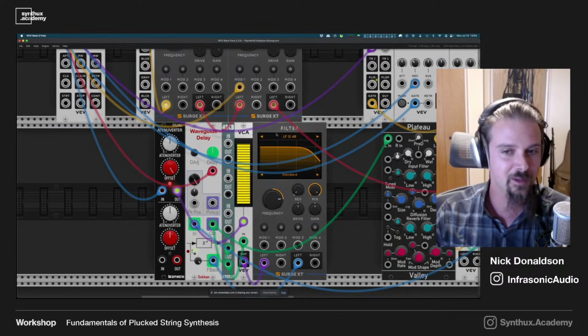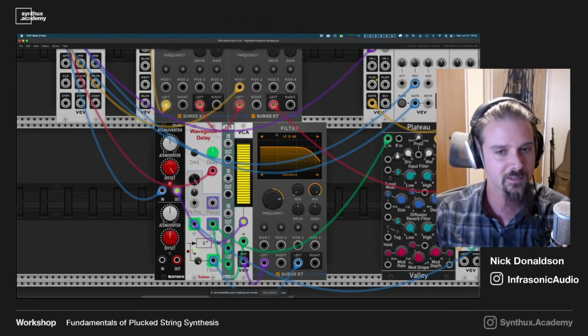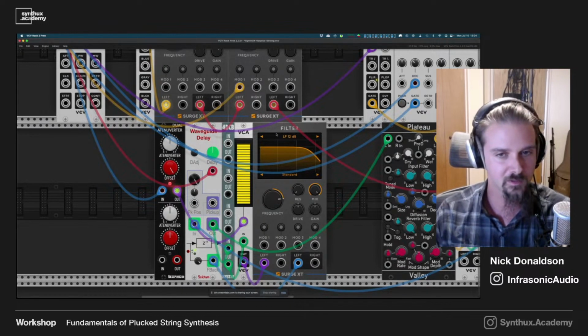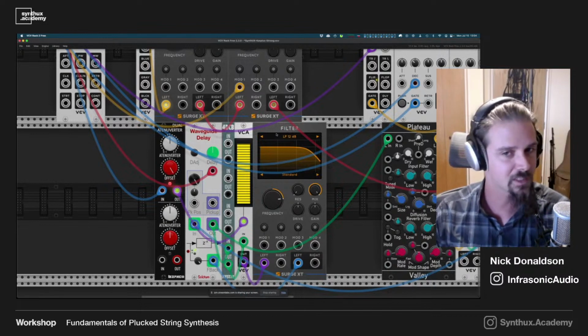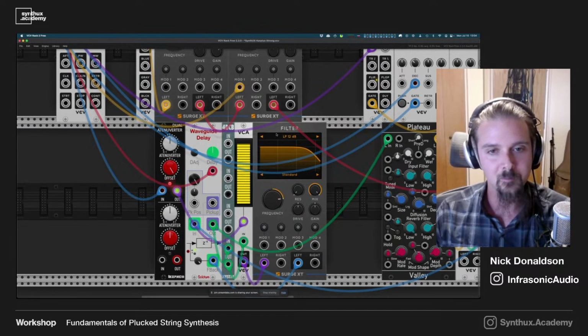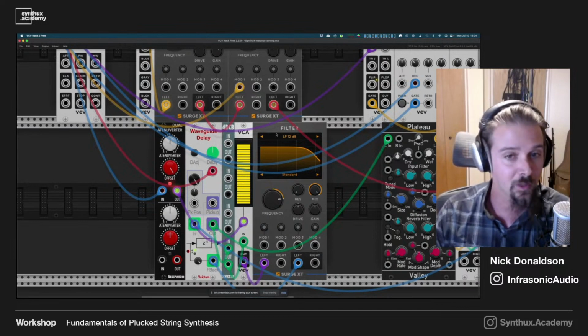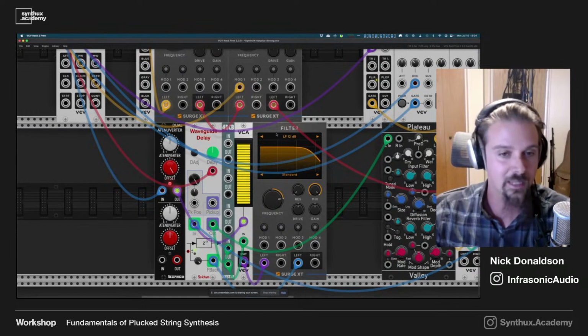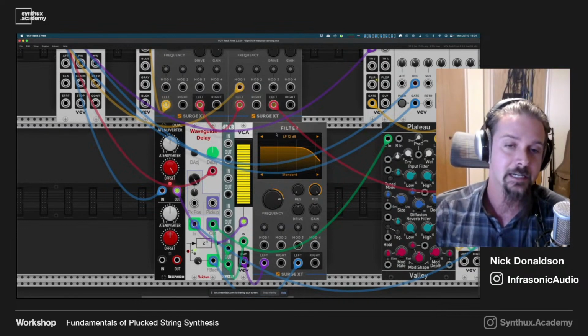I know that's maybe not the best explanation, but it's a little difficult to explain without really understanding digital filter theory. And I wasn't planning on talking too much about that in this talk. So suffice to say that the tuning is dependent on the overall phase response of whatever, and additional delay of whatever you have in your feedback loop.